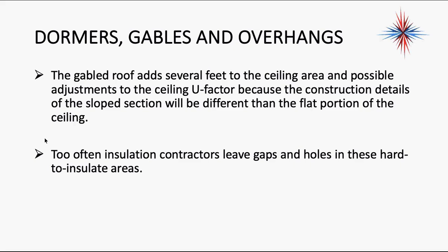I could pull up to a house, and if the rest of the buildings around have snow on the roofs, I can tell you if there's an insulation problem or a ductwork leak by looking at the snow on the roof. The other easy way is infrared cameras. They work really well.